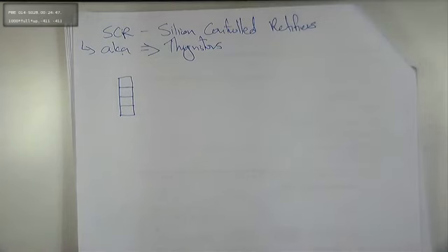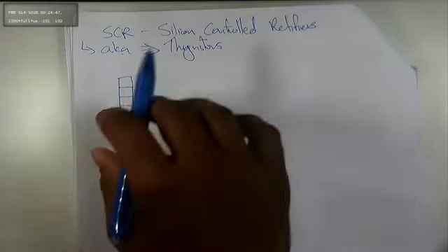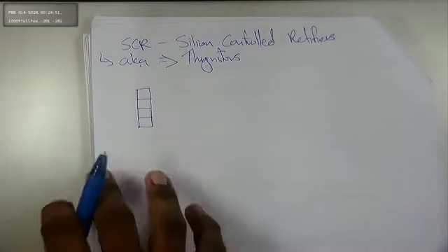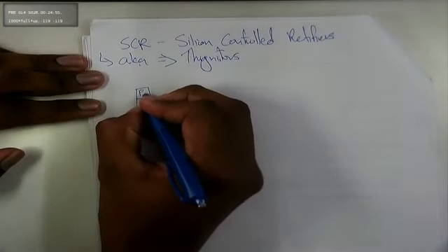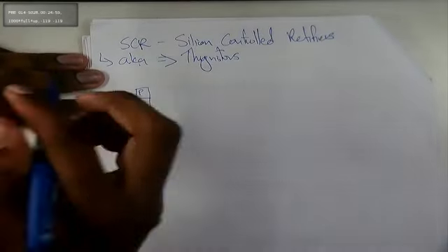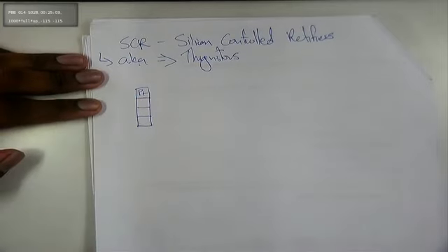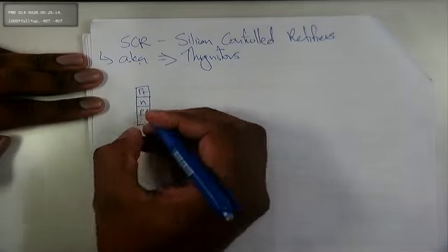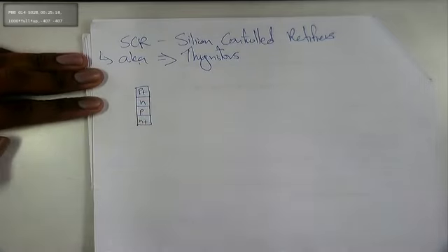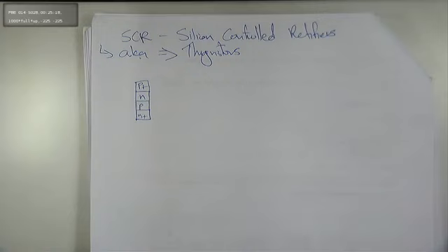So coming back to thyristors. Our thyristor looks something like this. First we have P, which is heavily doped. I hope you remember what doping is. Then N, and then we have another P, and then we have an N, which is heavily doped again.